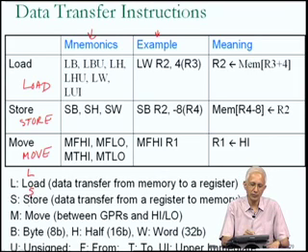An instruction that starts with the letter M is a move instruction. Whenever in this table we see a B, it stands for movement of a byte. Whenever we see an H, it stands for movement of a half word or a 16-bit piece of data. Whenever we see a W, it stands for movement of a 32-bit value.